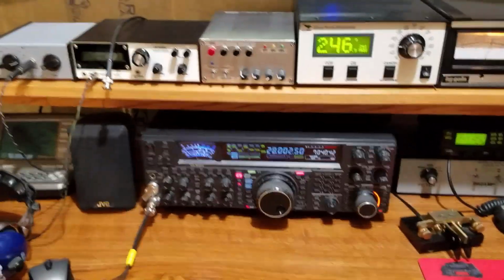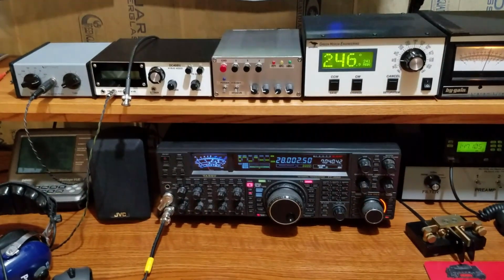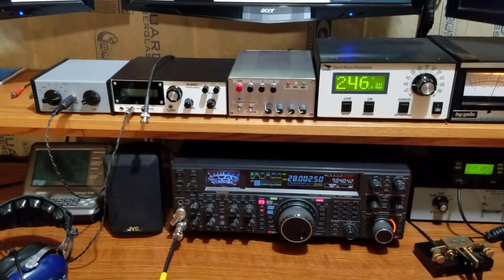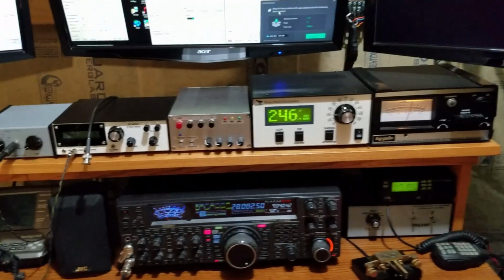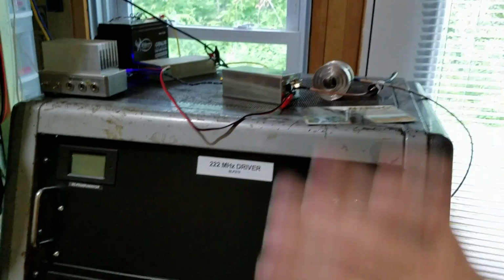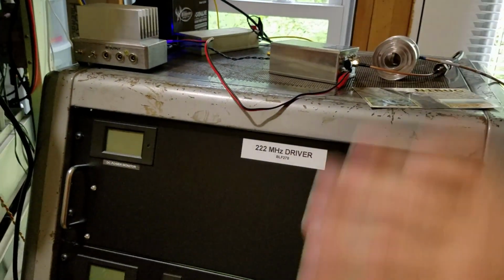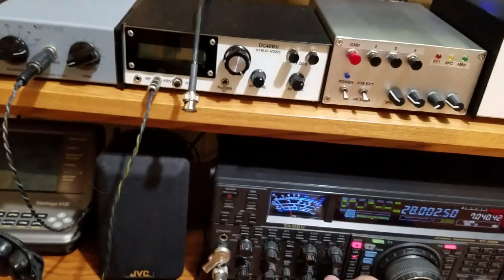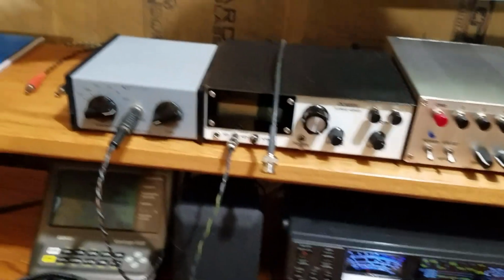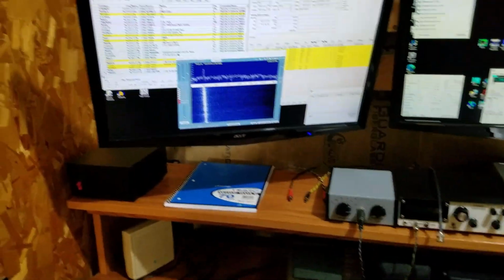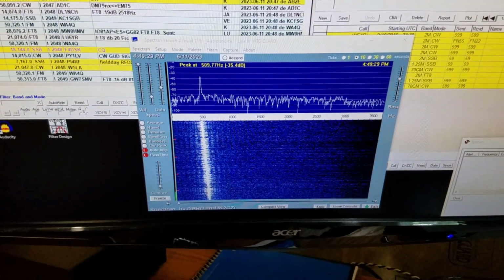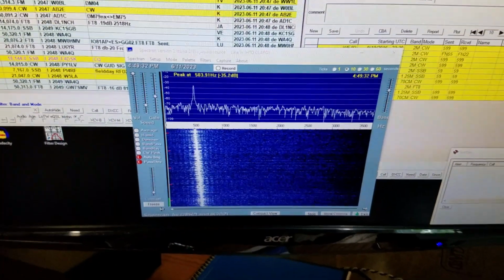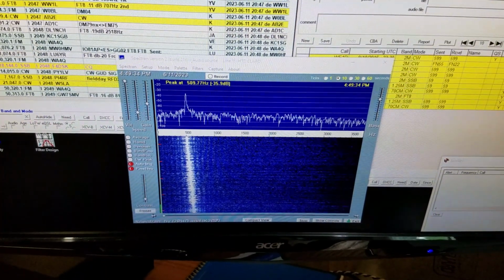That's Doppler shift from something moving in the field of RF. At 10 gigs, it's remarkable how anything that's moving reflects the RF and creates Doppler effects like that. Okay, so anyway, the receive on this thing definitely is working. And I've got one more test I'm going to try here in just a moment.